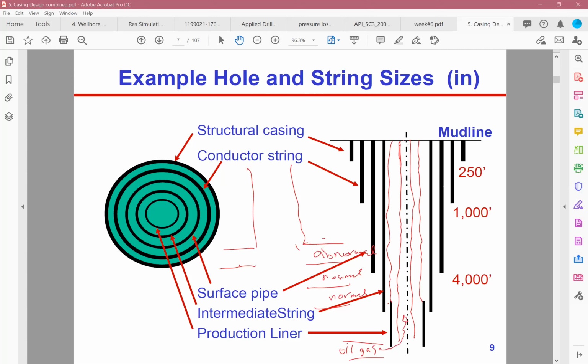So if you want to change your tubing later on, or do a repair or anything else, the production casing gives you the ability to work with your tubing and change it without disturbing other parts of your wellbore, because once oil and gas or other fluids are in contact with those pipes, they may corrode, right? And corrosion means that your pipe will have a problem. You may have a leak later on. So this production casing again isolates your system from the oil and gas that is coming out of the wellbore. Any questions so far?